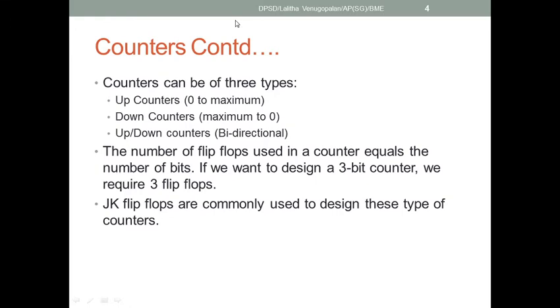Having said that, it does not mean that JK is the only flip-flop you can use for counter design. You can do it with T flip-flops or D flip-flops as well. Since JK is popularly used, I'm going to describe the counter design using JK flip-flops, but the same principle can be applied if you are designing one with T or D flip-flops.